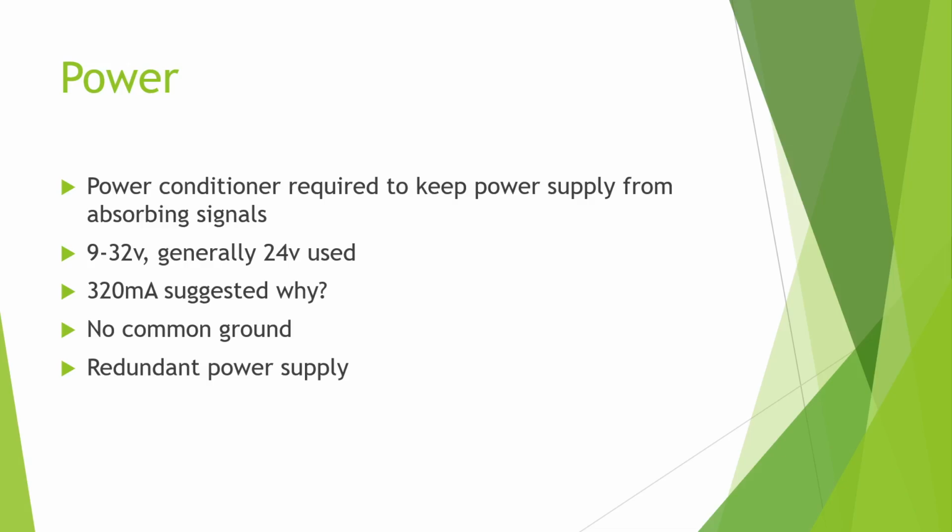Okay? This little one that I had, this is a 5 volt, 800 milliamp power supply. So that is a switch mode power supply in there. You actually go to like an old school one of these, you have a transformer that's probably about that big and weighs about a pound or whatever, compared to these little power supplies that we have nowadays. And they're only getting smaller. I don't know if you guys have realized that. It's like, oh, yeah, that's a 50-watt power supply, and it's the size of this thing nowadays. It's like, holy crap. Right? This is like a 4-watt power supply. 5 watts, 5 volts, 800 milliamps. So yeah, 4 watts. So we're coming a long way with power supplies.